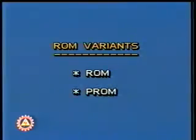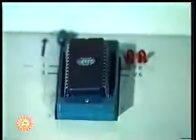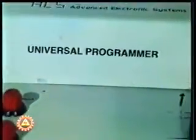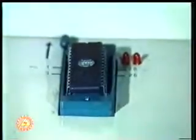In programmable read-only memory, abbreviated as PROM, the contents are programmed by the user only once, just similar to photographic plate or film. Erasable and programmable ROM, abbreviated as EPROM, is one where contents can be erased by ultraviolet light through a quartz window. And the contents are programmable more than once by a device known as PROM programmer.